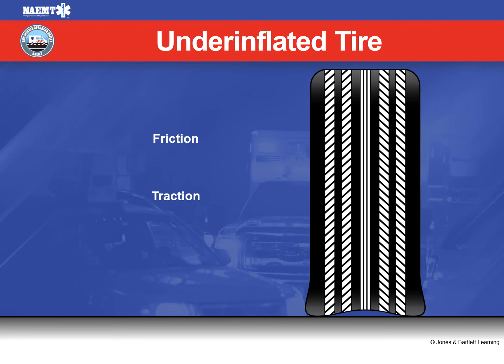Now, when tires are underinflated, they don't go flat. They actually pucker inward, creating a space between the tire and the roadway. They lose surface area of the road, only riding on the two sidewalls of the tire, which are the weakest part of your tire. The sidewalls absorb all the heat from the road friction, which will lead to a blowout. The tire shown has very poor traction, providing very poor handling, cornering, and stability.